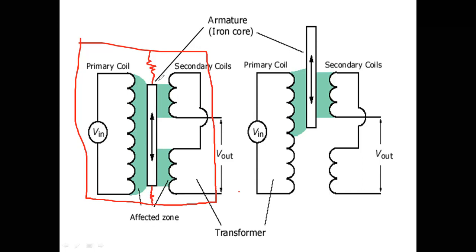So, for example, if the stiffness of the spring is lost here due to temperature or high vibrations, let us suppose, then what will happen? The core will not be exactly at the center. Okay, means I am not applying any input here. Input for the instrument is displacement.